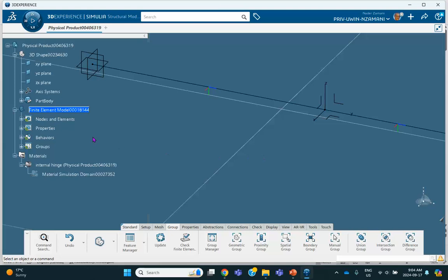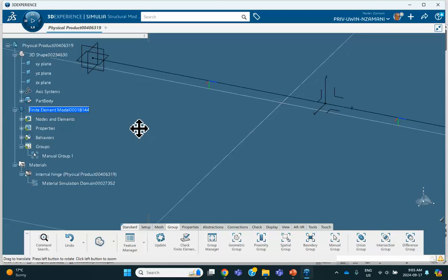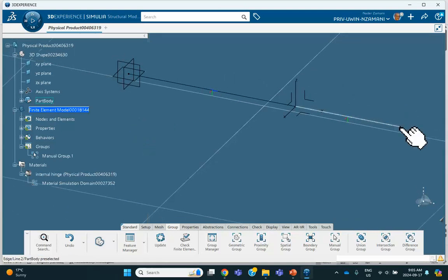This group has been created right there. I could have called it, for example, node, or location of the concentrated force. But that's fine. I don't need to do it at the ends because the ends seem to be immune to it. Although, if you have any doubt, you can create a left group, right group, and call this one middle group so that you know exactly what is what. But for these endpoints, I really don't need to create the group. You can do it, as I said, but it doesn't matter. Now, that's pretty much it.